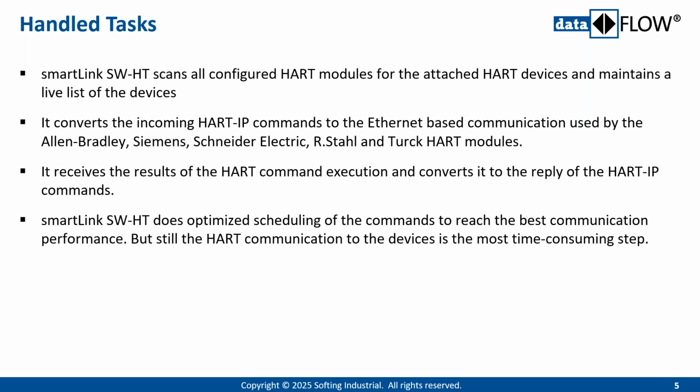Then, if it has this live list established, it waits for incoming HART IP commands from the asset management application, and then transfers these commands according to the configuration to the right tunneling protocol for the controller. So in the Siemens case here, it uses that HART IP information and encapsulates it into a Profinet communication to the CFU or the ET200 devices. Then it sends this HART request to the device, waits for the answer from the HART device, which is provided via the remote IO, and then of course sends that back to the asset management application.